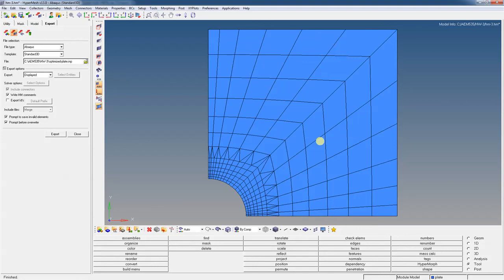Some things can be pretty complicated to model, and they may not just be interested in stresses, they might be interested in displacements, natural frequencies, or something like that that maybe doesn't require as fine of a mesh. In our class and for your academic career, I'd really urge you to do convergence analyses for any finite element analysis that you do. And it's something that you do need to keep in mind if you're a practicing engineer, that you're going to need to understand convergence behavior.